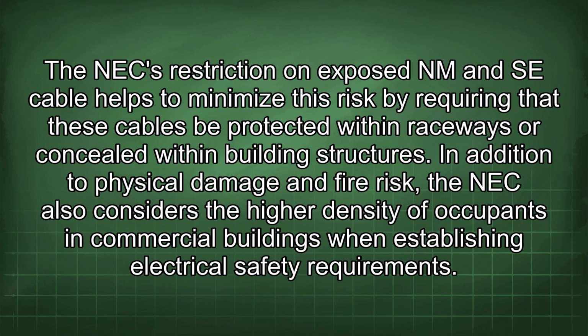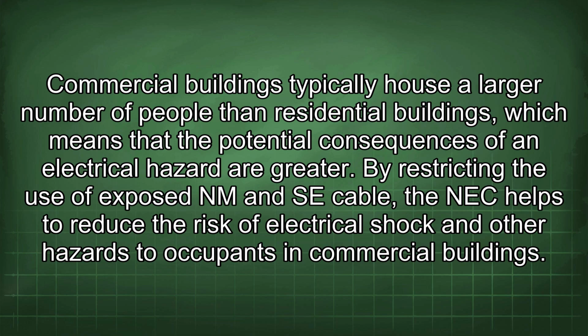In addition to physical damage and fire risk, the NEC also considers the higher density of occupants in commercial buildings when establishing electrical safety requirements. Commercial buildings typically house a larger number of people than residential buildings, which means that the potential consequences of an electrical hazard are greater. By restricting the use of exposed NM and SE cable, the NEC helps to reduce the risk of electrical shock and other hazards to occupants in commercial buildings.